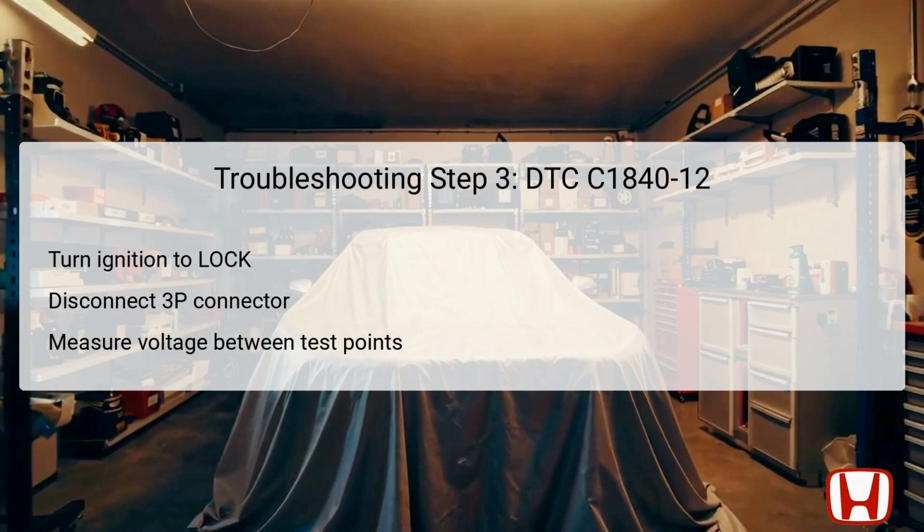For troubleshooting step 3, begin by turning the ignition switch to the lock position to ensure safety during diagnostics. Next, disconnect the rear differential fluid pressure sensor 3P connector. Following this disconnection, turn the ignition switch to the on position, ensuring that the system is powered while you proceed with voltage measurement. With the HDS not in operation, measure the voltage between the two specified test points, which include number 1 at the gray wire and number 2 at the pink wire of the 3P connector.